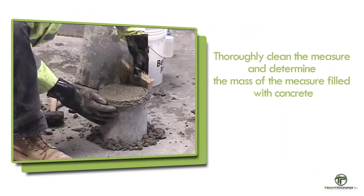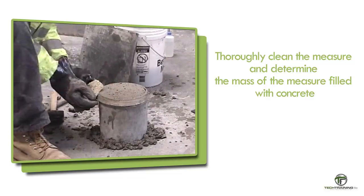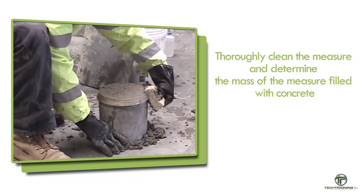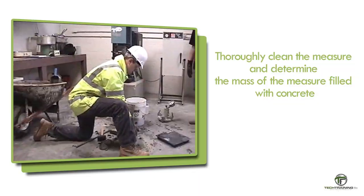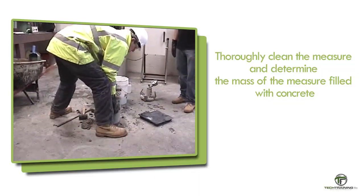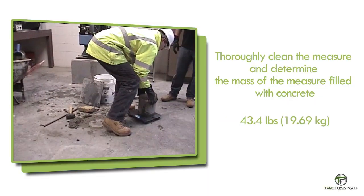After strike-off, clean all excess concrete from the exterior of the measure and determine the mass of the concrete in measure to the nearest 0.1 pounds, or 0.01 kilograms. For our example, assume the weight to be 43.4 pounds, or 19.69 kilograms.